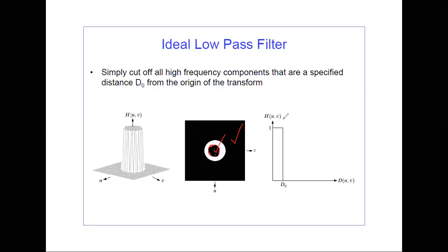Now what does that mean? What sort of filter would that be? It's going to be a band pass filter. Say this particular radius from the center is D1, and the outer radius is D2. Wherever there is white, a 1, the values will be forwarded as they are. Wherever there is black, the values are suppressed.